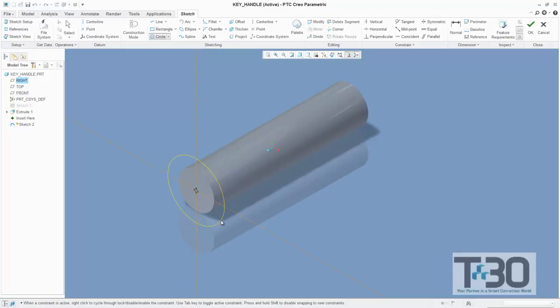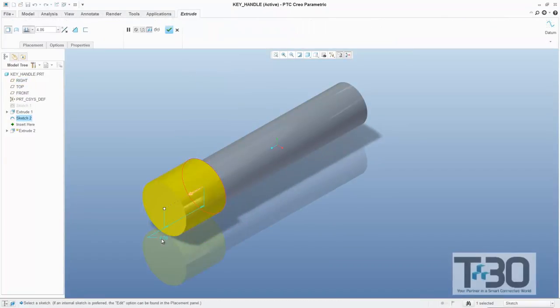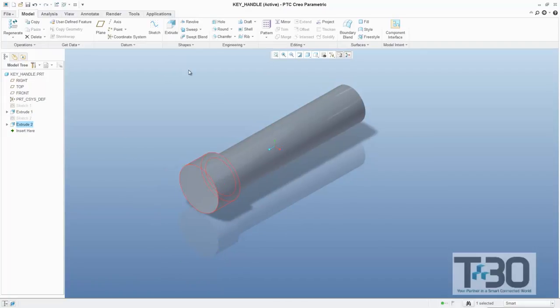Oops, I forgot to click. Left mouse click and then middle click to get up the dimensions. We're going to go ahead and type in 4.5 inches here. We're going to hit OK. We can then extrude this. Let's set this to be about 2.5 inches out. Now, this will be more exact when you have your engineering drawings. You'll have to follow that, but for right now, we're going to get an idea of what this handle should look like, and we can make adjustments as we go.